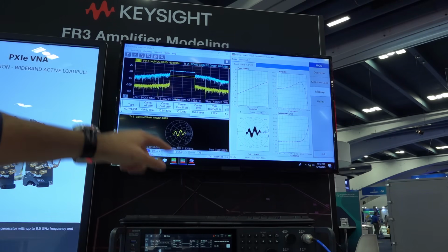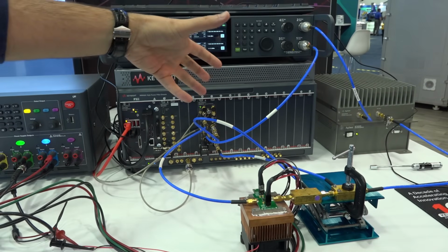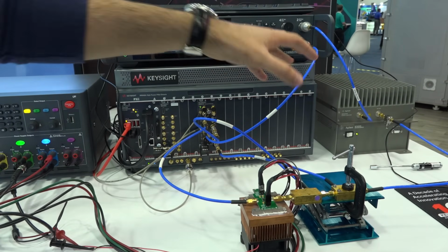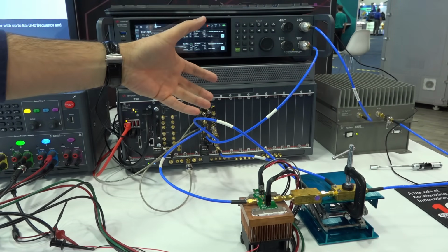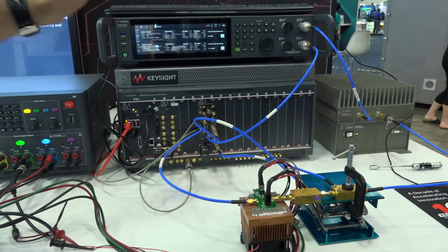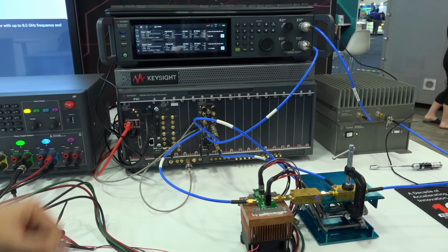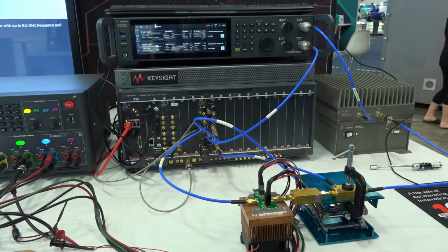This estimation of the EVM in one setup is really helpful, because normally what you'd have to do is capture that separately, because that's a dynamic time domain based system. Here you're doing frequency stitching to compensate for it, just doing all that in one setup. There's a lot going on here, but these active load pull systems are now more and more common, especially coupled with simulation results.